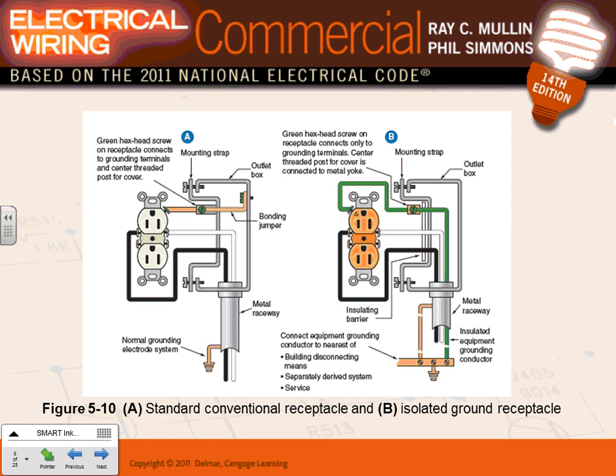Here are two receptacles. One of them is isolated ground, and the other is a non-isolated ground receptacle. I want to emphasize this right here. Can you see that the box, the frame, and the receptacle are tied to the same conduit, which is where you're getting the ground? So here's the ground coming into the box, grounding the box and grounding the frame.